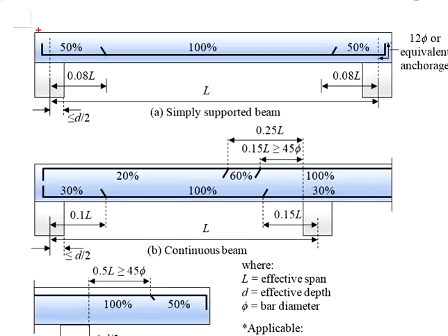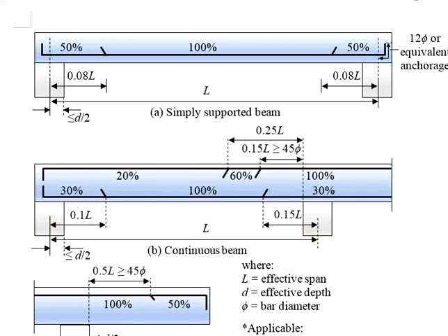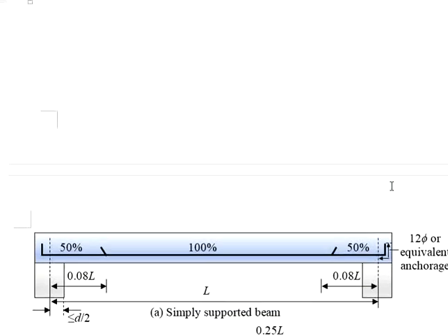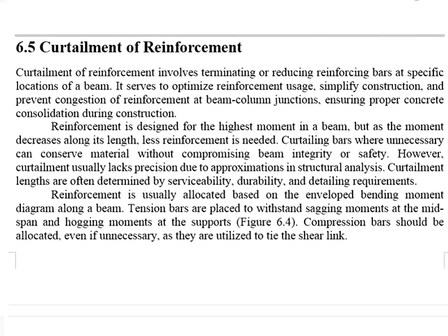That's why in the typical simplified rules for the curtailment, they allow for a certain degree of tolerance, allowing slightly greater resistance than what is required in order to cater for such inaccuracy. And then bear in mind that the outcome of the curtailments may not necessarily be ultimate, as it tends to be influenced by the other serviceability, durability, and detailing requirements.